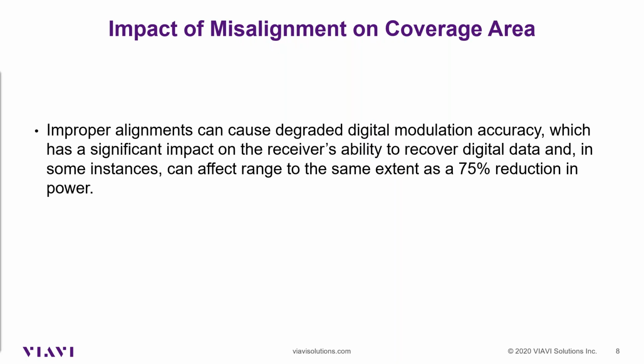So there's some obvious things that affect coverage. I talked about bridges or new walls or new buildings going up. Interestingly, misalignment of radios is probably a more common cause. Obviously, those things do happen. We do have lightning strikes. We do have cables that get closed in doors or have staples driven through them and things like that. But a more widespread, maybe I shouldn't say more often, but a more widespread thing that happens is our radios are misaligned, and that can happen through aging of the components. It can also happen due to misalignment because of not using the right equipment.